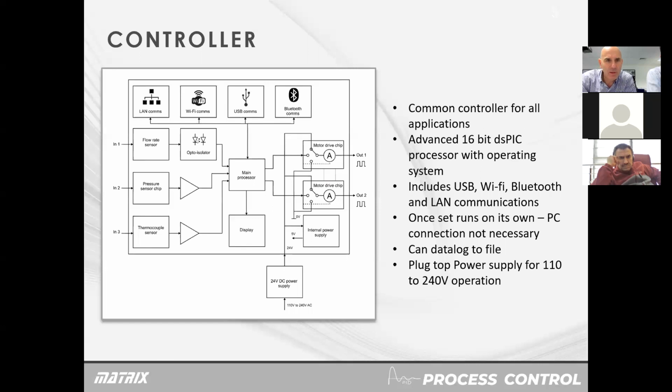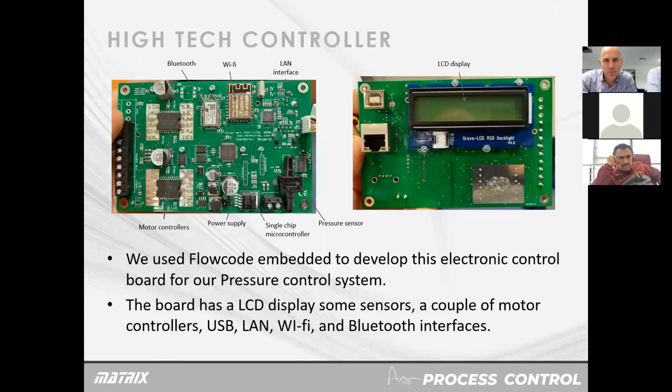It's got some inputs and some signal conditioning and a couple of motor drivers, and then a power supply. So the overall topology, if you like, is fairly straightforward, but the software is what makes it really good. So the API is like a little mini operating system that comes with it, which does data logging and control. There's no external controller needed. Everything is provided in every rig. So there's no external sort of data acquisition systems needed.